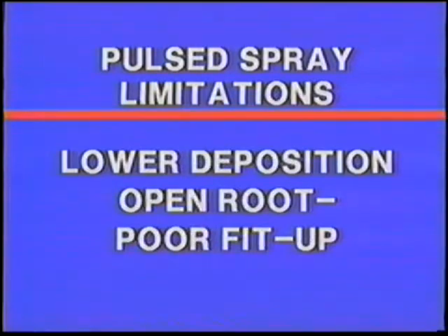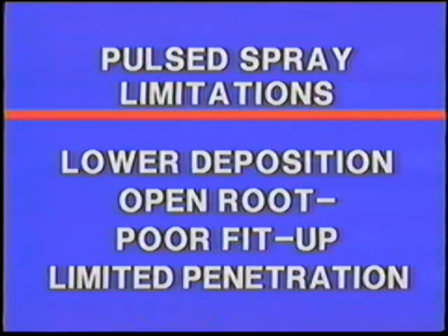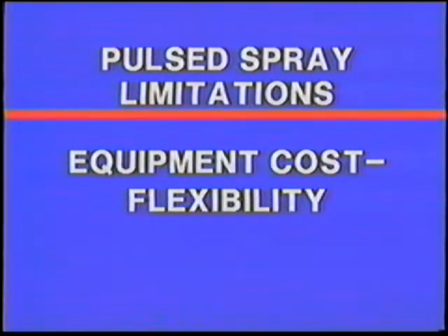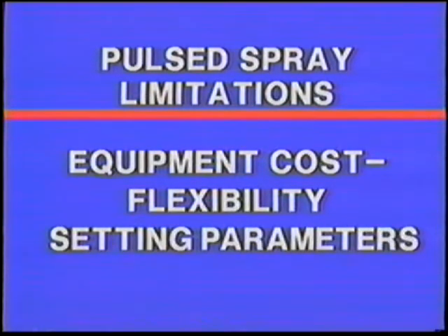Some of the pulsed spray limitations are lower deposition than spray transfer due to lower wire feed speeds, limited use of open root or poor fit-up. Low heat input results in limited yet adequate penetration. Cost of machines increase as sophisticated controls are developed. Ease of setting parameters has been improved with developments of synergic type controls. Pulsed spray has many advantages for certain applications. As technology advances, new applications will no doubt be uncovered.